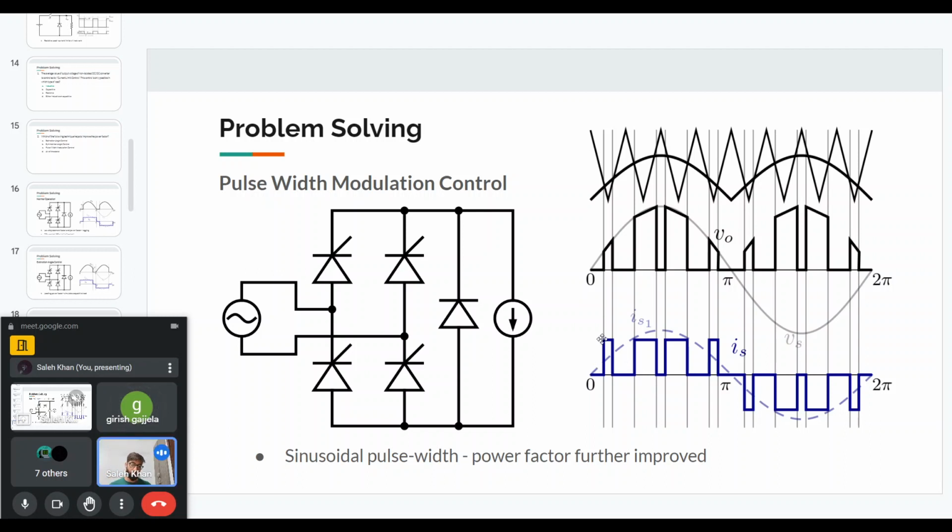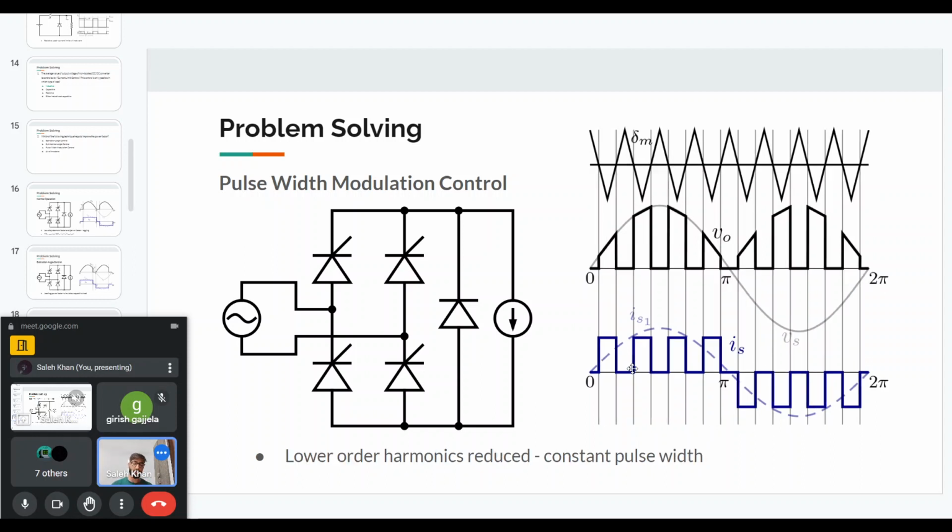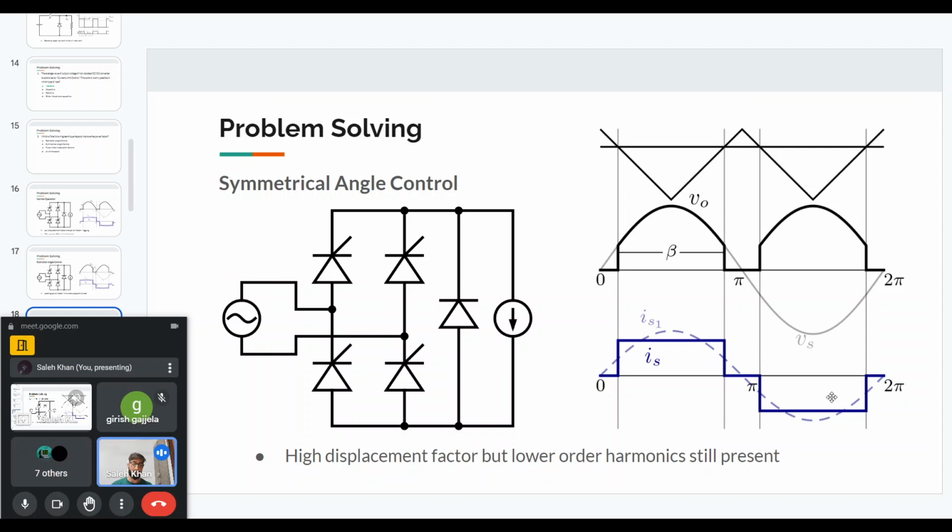Yeah, you can understand because if you see this waveform, it has a high frequency component, and this high frequency component has a larger amplitude compared to the normal square wave. You have the square wave or the quasi square wave. In that case, the fundamental will have a high amplitude. The lower order harmonics will have high amplitude, but as you go higher in the harmonic spectrum, the amplitude will reduce for the quasi square wave, a wave like this.